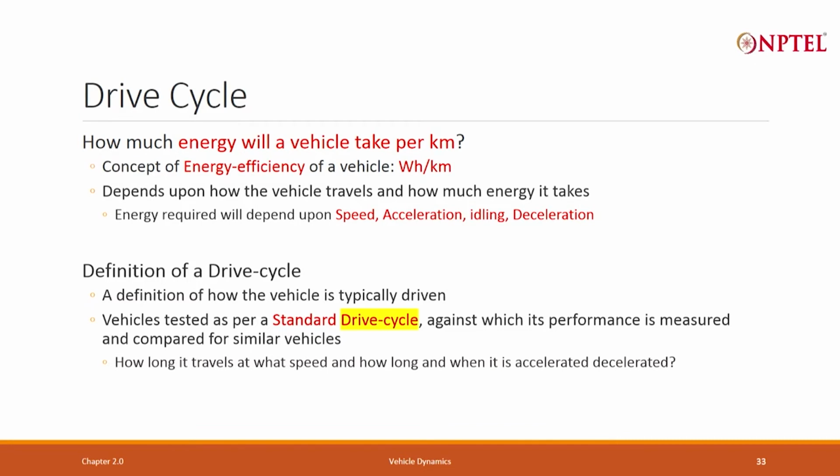The standard drive cycle will tell you how long you travel, at what speed you travel for how long, how much you accelerate, how much you decelerate, whether you wait or idle. It will define this, and for a class of vehicle, it will standardize it, and that is called a standard drive cycle.